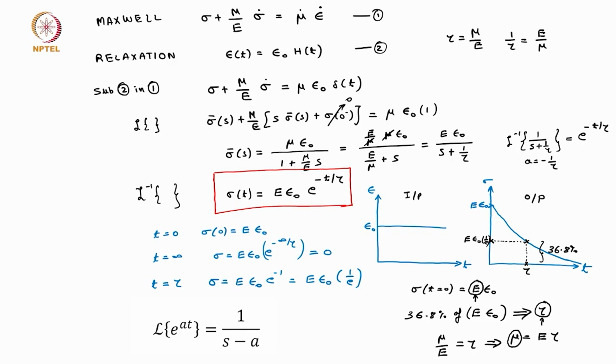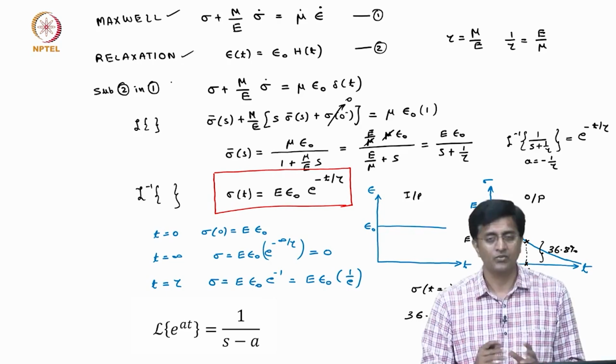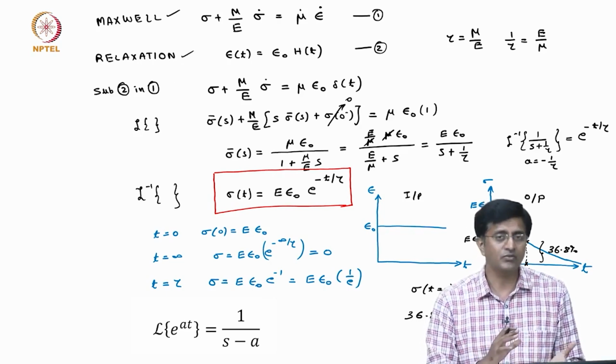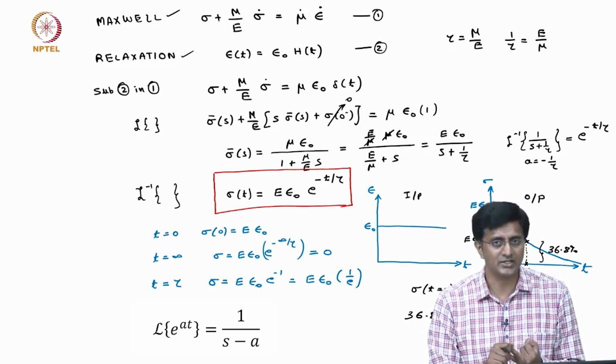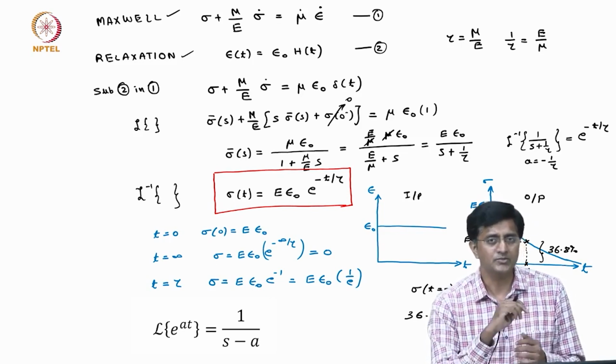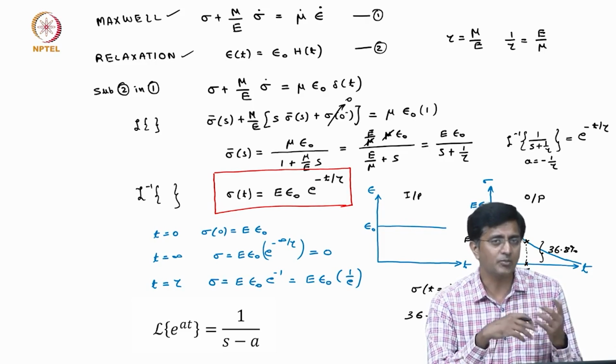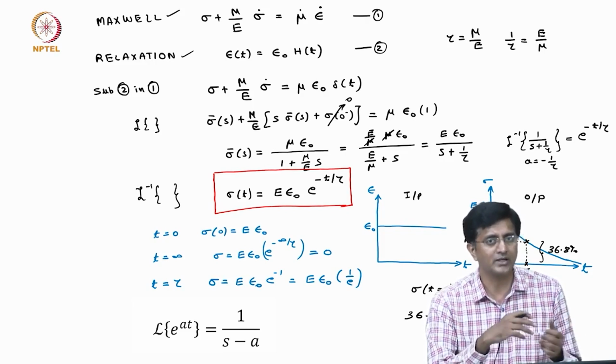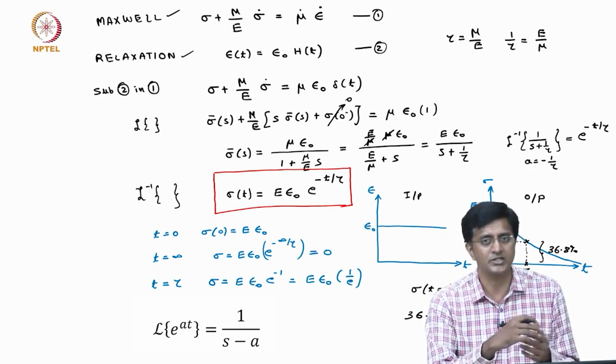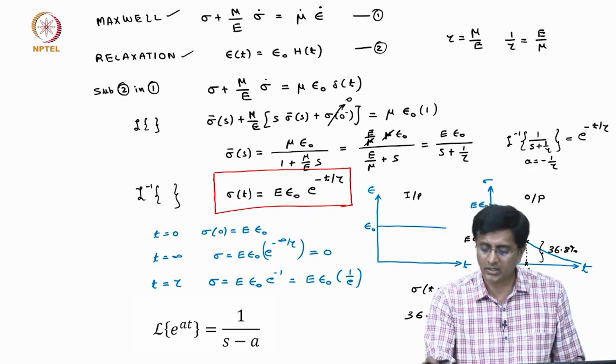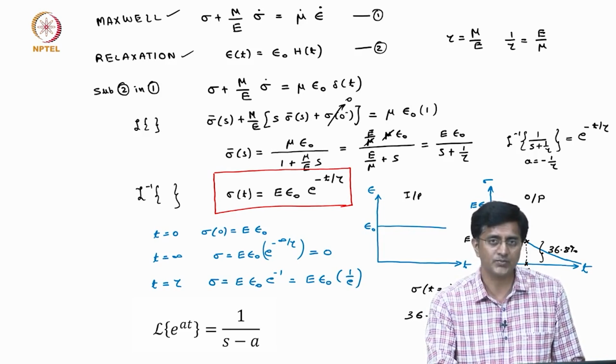Okay. So, what we have seen in this slide is we derived the stress response when a Maxwell model is applied a relaxation load. Finally, we are done with the creep loads and the relaxation loads, but sometimes it is not just the creep and the relaxation loads; there are many other loads people use to conduct experiments or to characterize viscoelastic materials. So, with that motivation, let us also look at the response under constant strain rate loading.